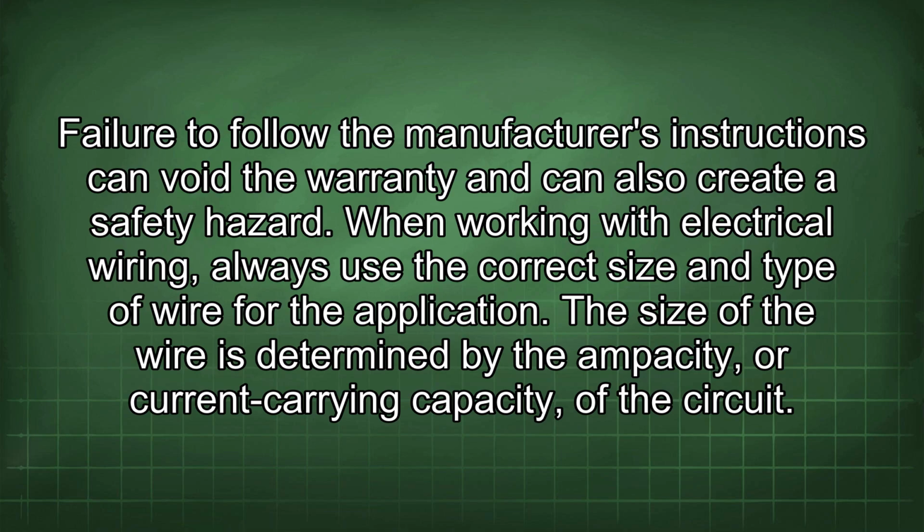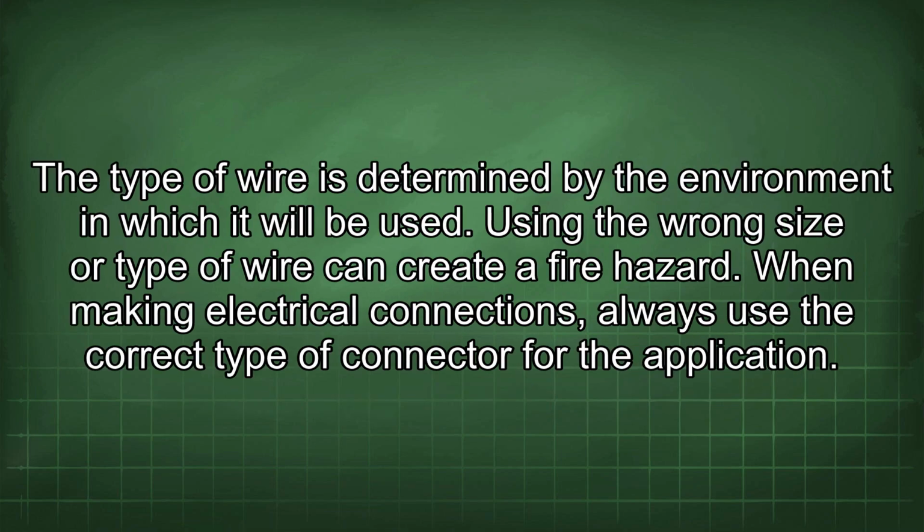When working with electrical wiring, always use the correct size and type of wire for the application. The size of the wire is determined by the ampacity or current carrying capacity of the circuit. The type of wire is determined by the environment in which it will be used. Using the wrong size or type of wire can create a fire hazard.